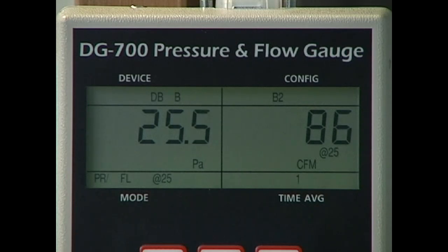This is unnecessary because the specialized pressure flow at 25 mode will automatically adjust the measured total leakage rate to the test pressure. Once you're done adjusting the fan, channel B will now be displaying the measured total duct leakage rate in CFM. In this demonstration, the total duct leakage measurement is 86 CFM, using ring 2 on the duct blaster fan. You should write the leakage measurement down for later entry into program forms or software.